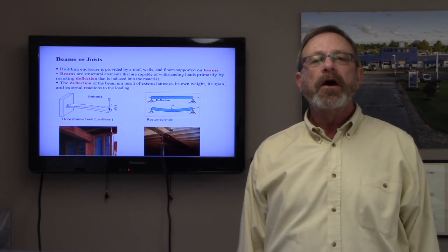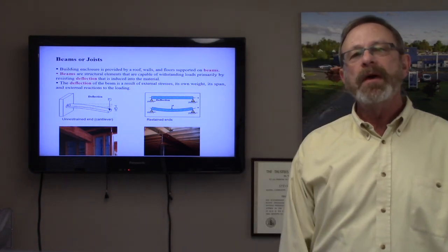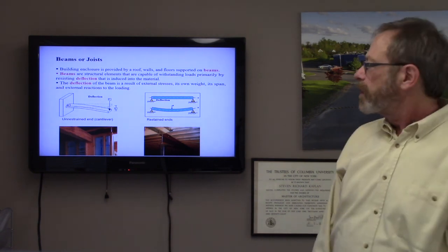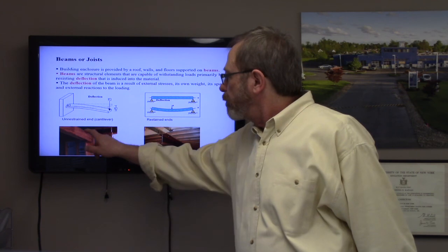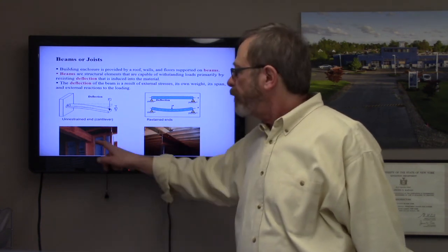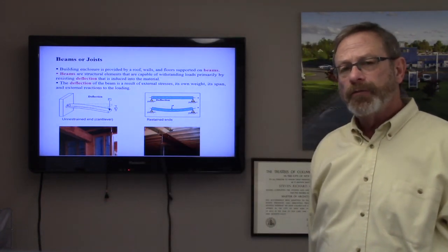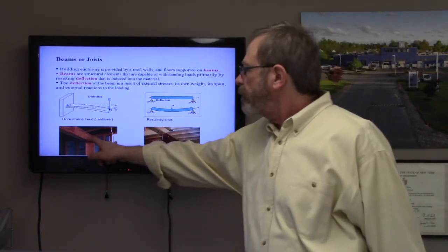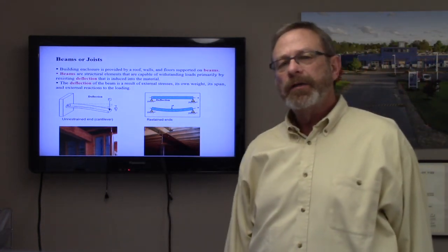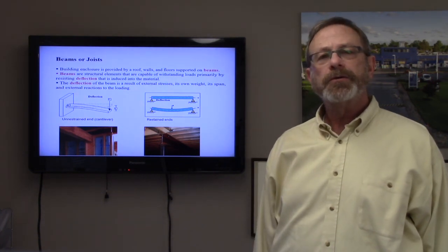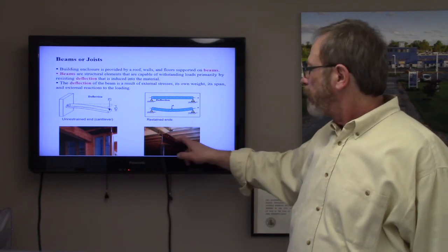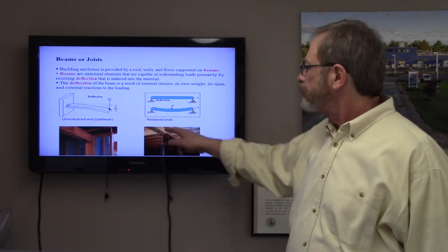Beams generally are the supportive system for smaller framing members, which in turn hold up the roof beams called joists. So here we have some horizontal framing members. These could be called beams, but because there's something larger that's also a horizontal member, we call this the beam, and we call that a joist. So joists and beams are synonymous depending on the hierarchy of the structural elements themselves. So here are some joists framing into a larger beam.